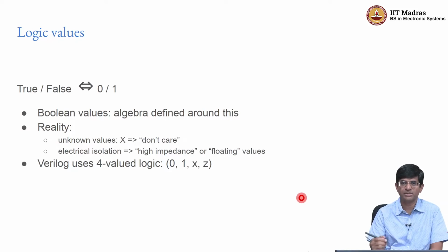When you switch on a system, there is no guarantee that all signals or all wires are going to be 0. We very often assume that that must be the case because after all 0 corresponds to a low voltage, and if you have not applied a voltage, how could something be at a high voltage, right? That's not how it works in practice. Very often there are capacitances inside a circuit, which means especially that if you switch off and switch on again very quickly, there's every possibility that a particular wire somewhere inside the circuit is actually still holding a logic 1 value, right?